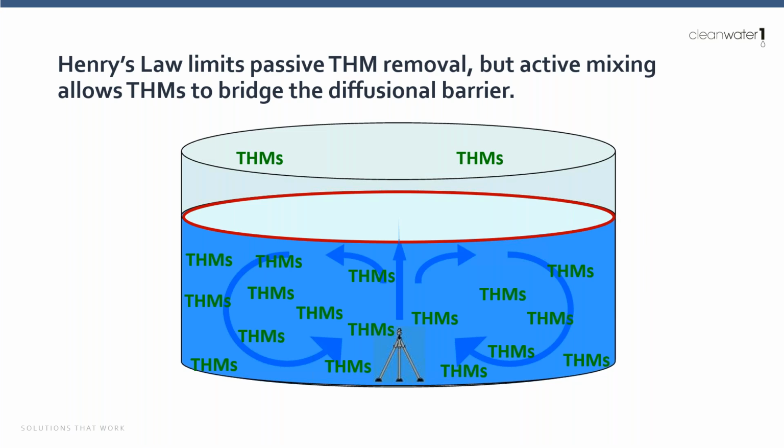And despite the fact that it's very old water, if you actually take the time to go in and measure the concentration of trihalomethanes in that layer, what you'll find is that the THMs at that top layer are not that high, because you've got some air exposure there at the air-water interface, and you have some turnover in the top of the tank. As the tank level drops and falls, it pulls air in and out.